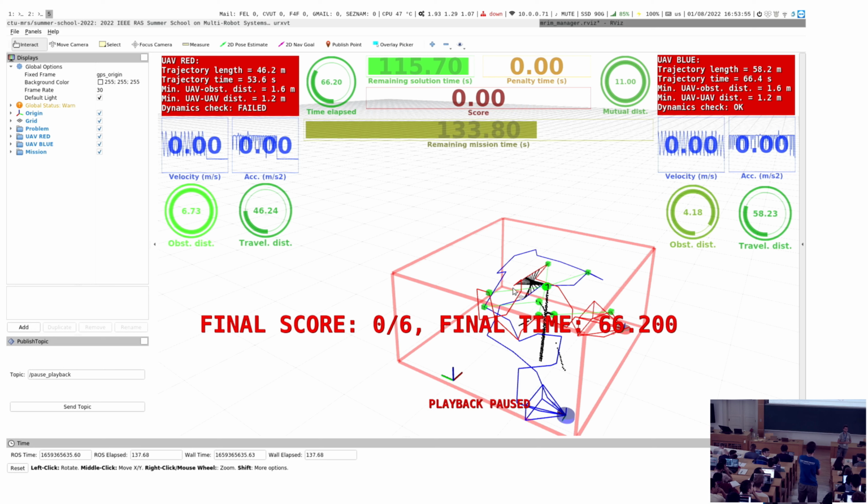I want to ask, in the PIXHawk controller, when you connect with MAVROS to the companion computer, how feasible would it be to run this code or this system on a custom self-made PIXHawk controller that maybe has a different companion computer, doesn't have the whole suite of sensors, maybe it has an RTK GPS but doesn't have a LiDAR? So totally possible. Our dependency on PIXHawk is quite low, I would say.